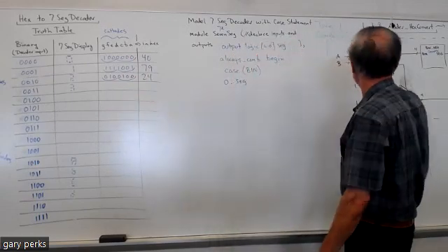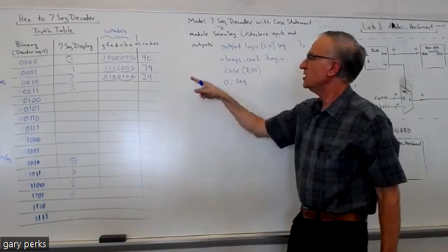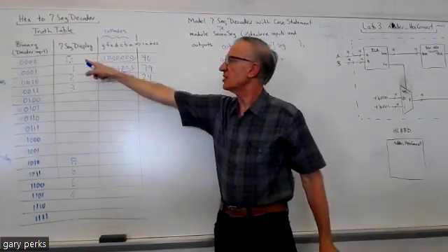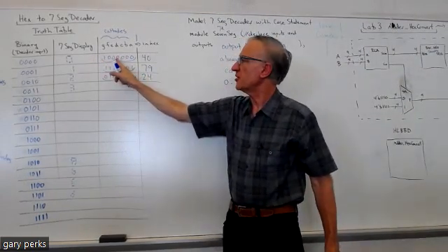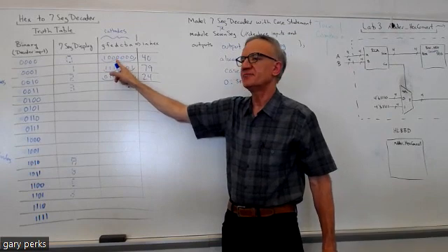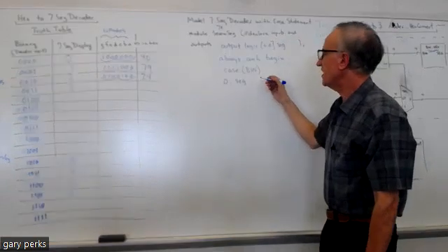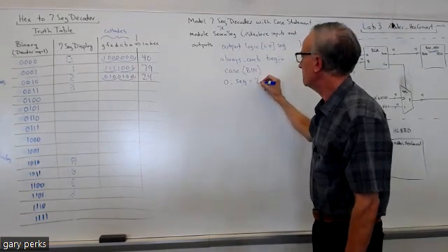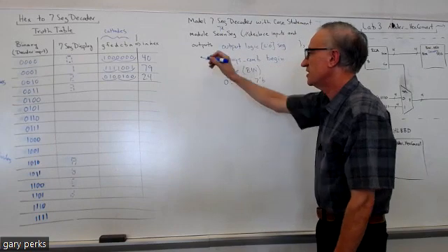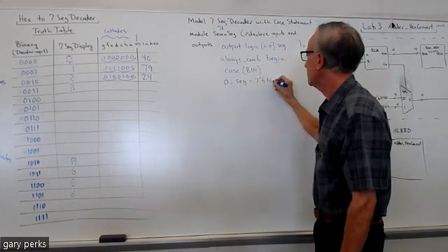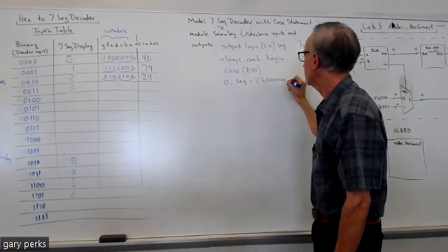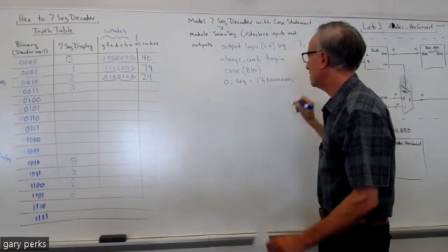So when we have a 0 going into our decoder, we want the display to show a 0, and it will show a 0 provided that the seg output is equal to these bit values. So you see, I would put seg equal to 7 tick mark B, then I just copy what I have in my truth table: 1 0 0 0 0 0 0 with these semicolons.